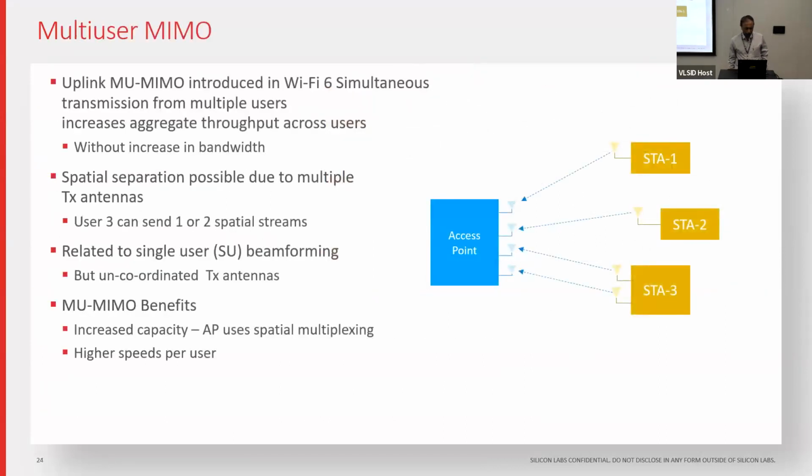And then today with Wi-Fi 6, you also have multi-user MIMO, where one station, which is an IoT device with minimal amounts of data, is sending something, but the capacity of that particular channel is so high that even though you can transmit, say, 2 gigabits per second, you're using it to send only 240 bytes. But still, that overhead and everything, the time slot is gone.